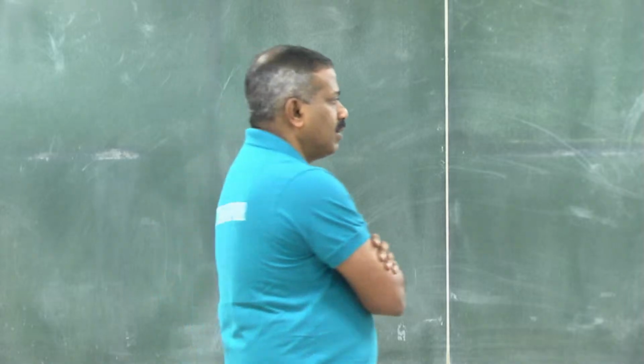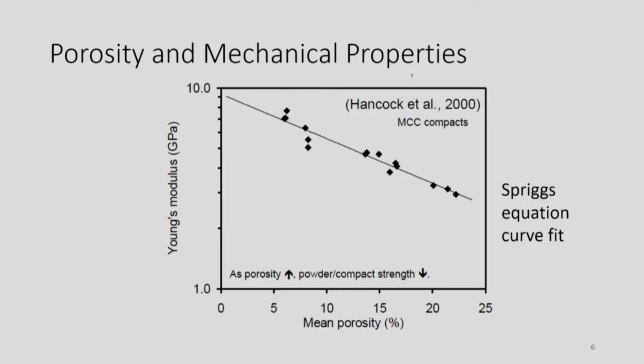So that's what you are doing, compacting at different forces. So you will compact at different forces, then you get compacts with different porosities. For example, if you're compacting at 50 megapascals, your void fraction will be different than when you are compacting at 100 megapascals. How will you know that for that pressure you will get that porosity? That's by experiment. You'll have to compact and then measure the porosity. First we have to compact the powder, after that we measure the porosity, yes.